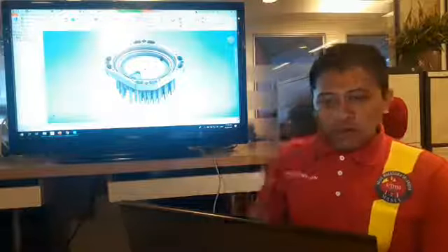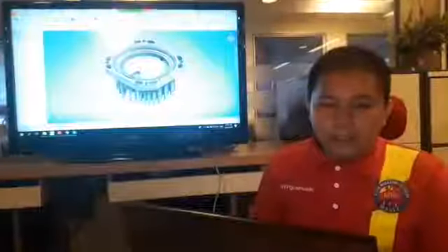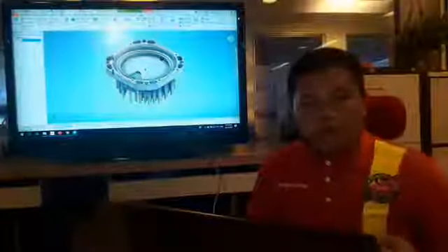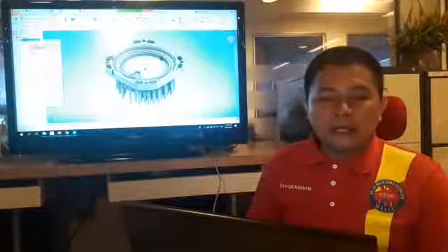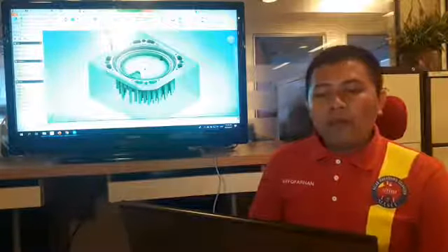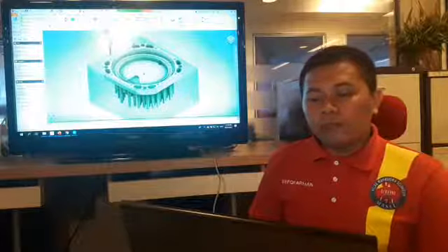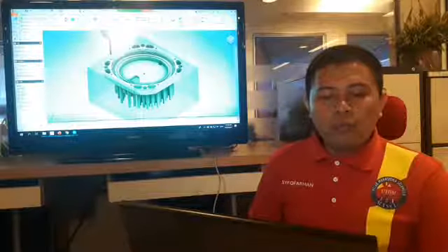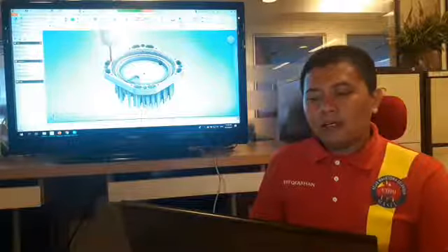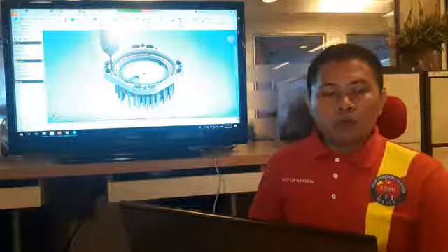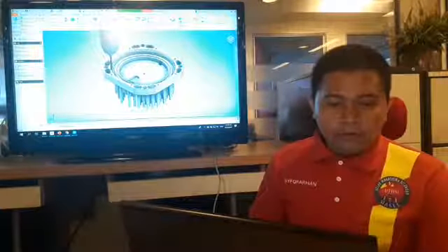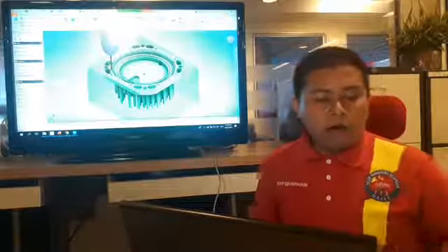Okay, so to make it simulate, you can simply click the job that you already created and do the simulation, or you simply right click and hit simulate. Now when you do the simulation, by default you will not have the stop. So just simply like this, right? If you want to ensure that your product is already cut properly, you just simply click on the stop over here.